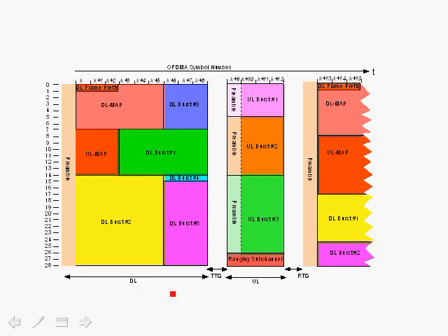We have the downlink subframe and the uplink subframe. In the downlink subframe, recall that we send a common preamble to all the subscriber stations, and then you have the actual maps and the data burst, the downlink data burst. Now what we want to point out is that in the downlink subframe from the base station to the subscriber stations, a common set of pilots are used that are common to all these subscriber stations.